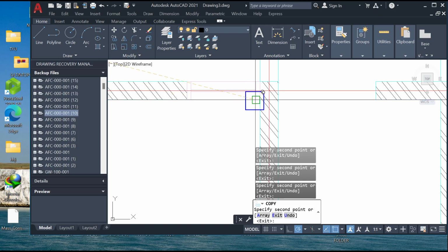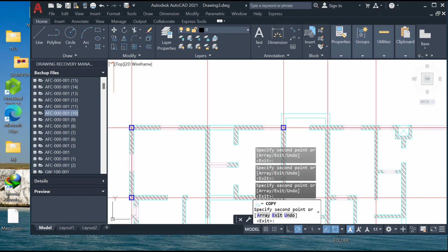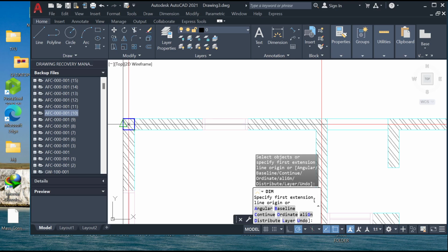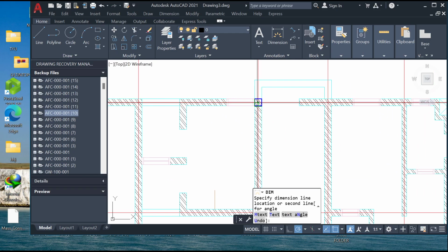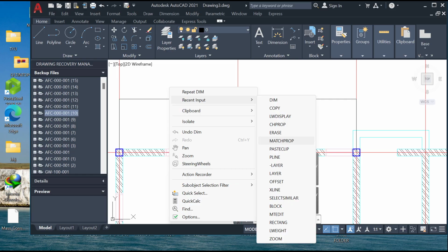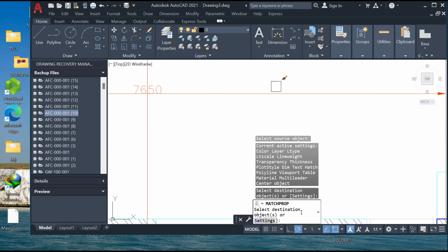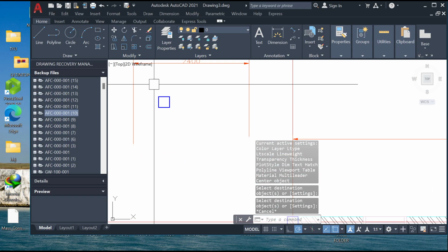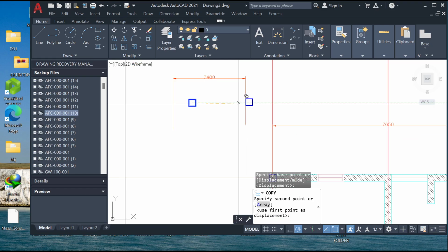Now if I place a column here, for instance, okay, let me show you what I'm saying. If I measure this now, the way I'm looking at this should be around 7 point something meters, but let's see. Now let's match properties. And see. This should be around 7. Okay, you can see that this is around 7.6 meters. Can you see that it's actually more than 5 meters? So when this happens, you now need to introduce a column to break the span.